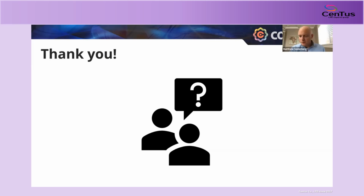Great, thanks, Carl. There's another good question that came in. It looks like, can you auto hex mesh based on mesh quality criteria? For that question, I answered that one to Pirkan just directly in the chat. But during our meshing process, we actually go through and do smoothing and readjust the mesh to the best that we can with the given geometry. But we don't have a given way that says create mesh of this quality or better, but we are automatically doing that with the given geometry. Thanks, Carl. Good question. That's an interesting question.